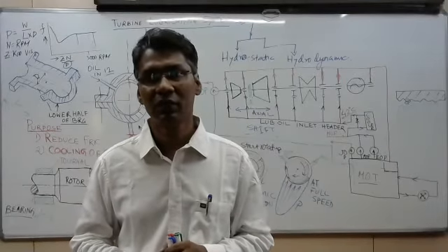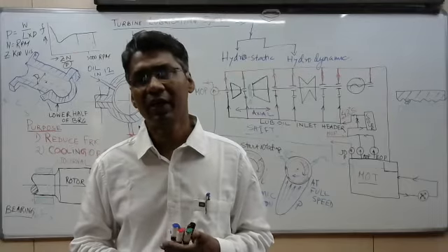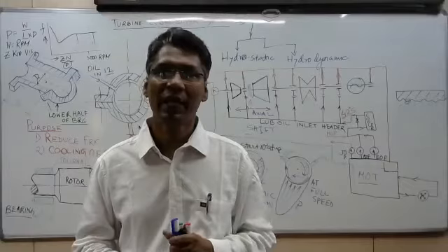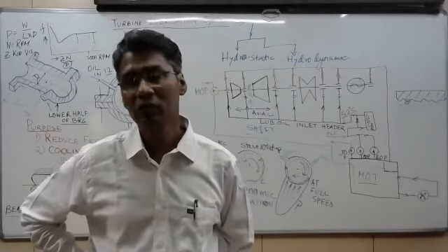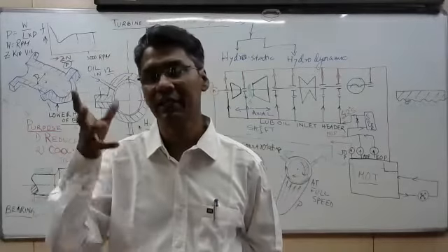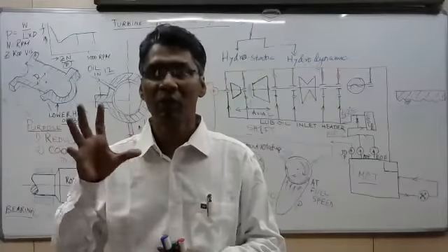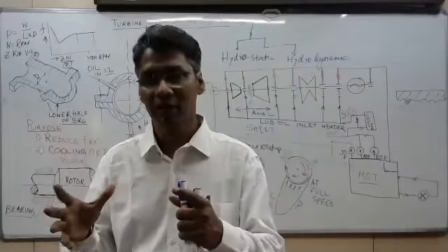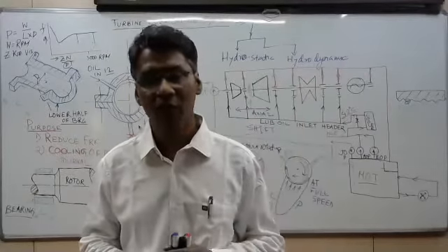There is a nitrogen cylinder also. What is the use of it, sir? I don't find any nitrogen cylinder in the turbine lube oil system. However, the power pack nitrogen cylinder is used in the HP-LP bypass system. A nitrogen bulb is provided inside the tank, so it is in compressed condition, and high pressure oil can be supplied continuously at any case. So that is a power pack. The nitrogen cylinder is provided in the HP bypass or LP bypass system, not in the main oil pump.